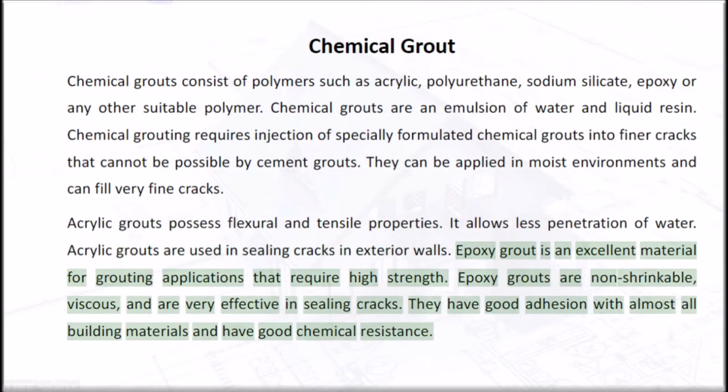Epoxy grout is an excellent material for grouting applications that require high strength. Epoxy grouts are non-shrinkable, viscous, and are very effective in sealing cracks. They have good adhesion with almost all building materials and have good chemical resistance.